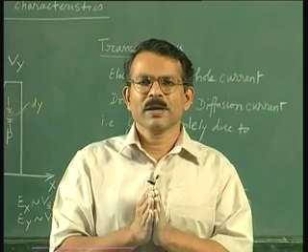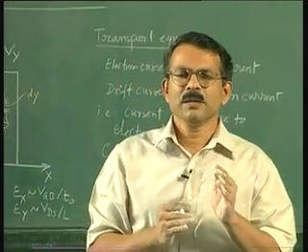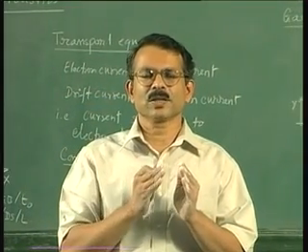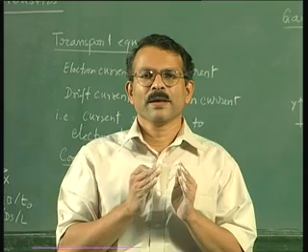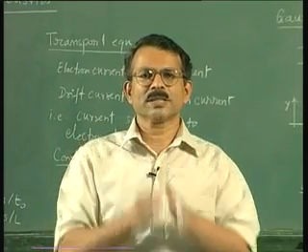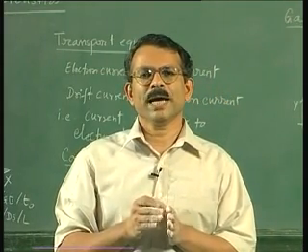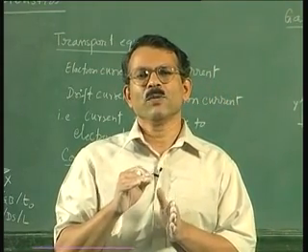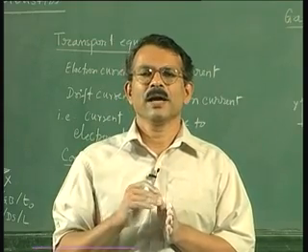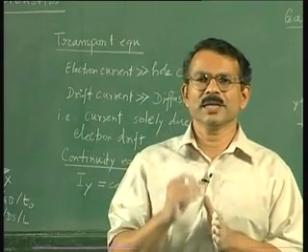So in summary, the 5 equations are used as follows: transport equation, no hole current and only drift current for electrons. Continuity equation, again no hole current and the current is constant with y, that is the statement of continuity equation. And Gauss's law, you assume that the picture is really one dimensional, that is in the x direction from gate to bulk, and based on that you find out the amount of charge. This is the so called gradual channel approximation.